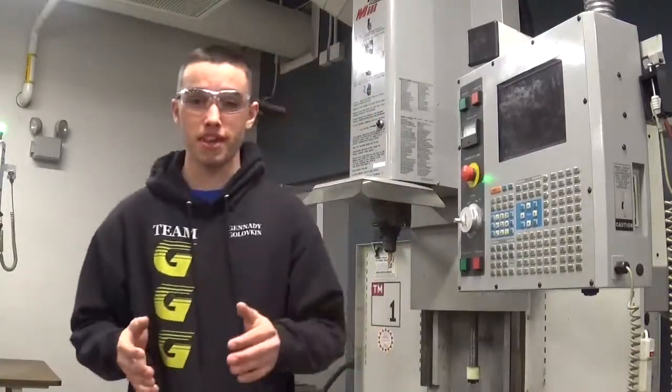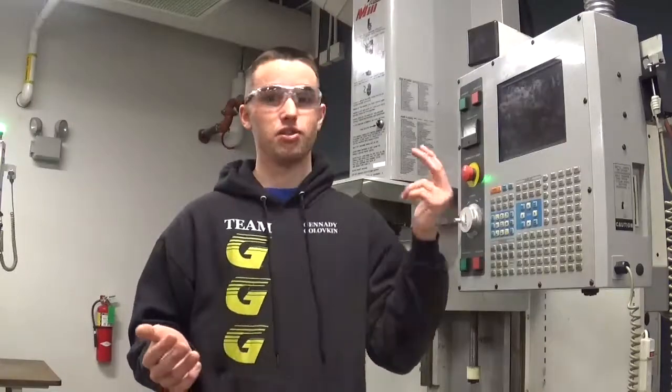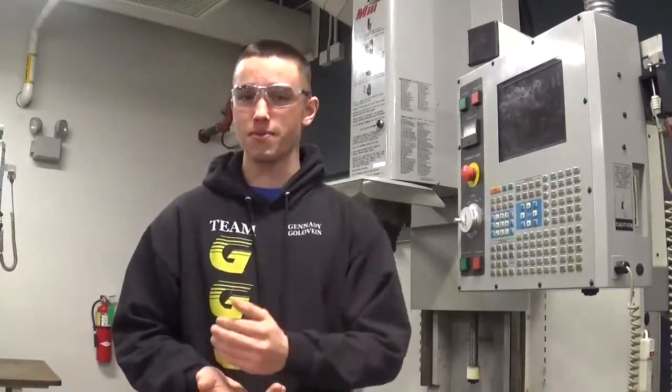I hope this video was a help to you. Just remember, with MDI, you can do anything with MDI that you can with the actual program. You can drill, you can mill, you can tap holes, anything you can do in a regular program you can do with MDI. MDI is a useful tool. Use it. It'll save you time. It'll save you money.